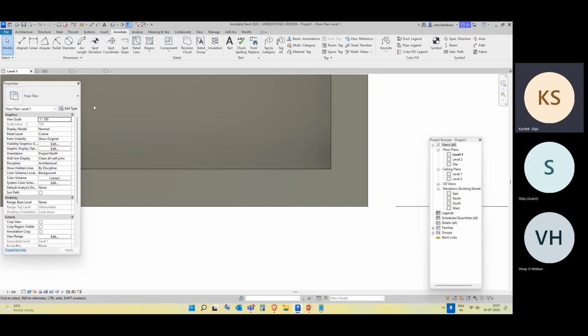Mostly the joint may not look perfect in Revit if it's a highly detailed area. In such cases, if that much detailing level is not possible, say there is an anchor bolt and you want to show how that anchor bolt is going to look, for that you have to go to this region or detail line. You have to take one more tab here.